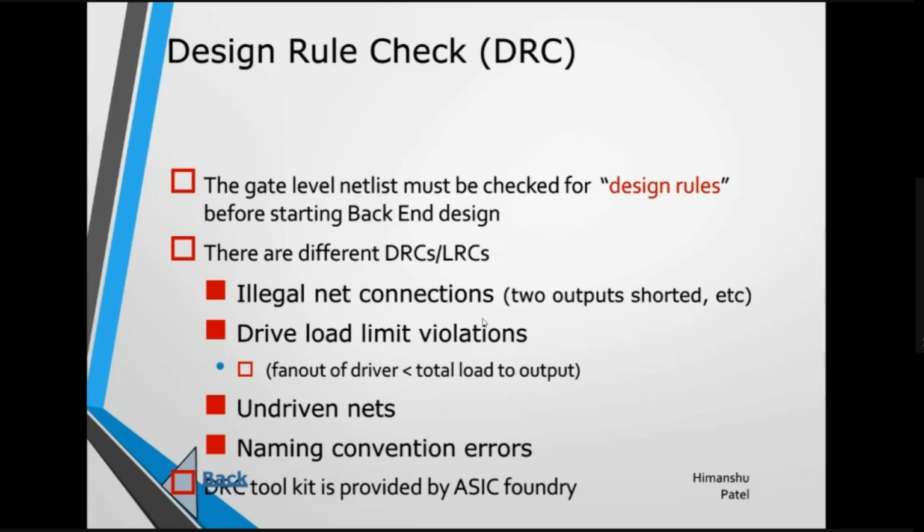It will say, okay, these are the DFT rules, pre DFT, post DFT. So pre DFT, the design rule checks are okay. In order to convert this entire design into a DFT friendly or scan inserted design, I have these rules. The tool will say, the data path should be very clear. Clock should be driven directly from the primary input. Reset should be controlled directly from the primary input. All these kinds of rules are nothing but the design rule checks.